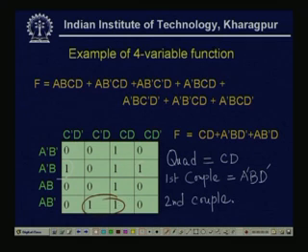For the second couple, that row is A B bar, that will be there, because both the adjacent ones exist in the same row, and for the two adjacent columns, C and C bar vary, that means they will cancel and it will be D. So, these are C D, A bar B D bar, A B bar D. Now, see this is my reduced function, that F equals C D plus A bar B D bar plus A B bar D. So, this is my reduced function.